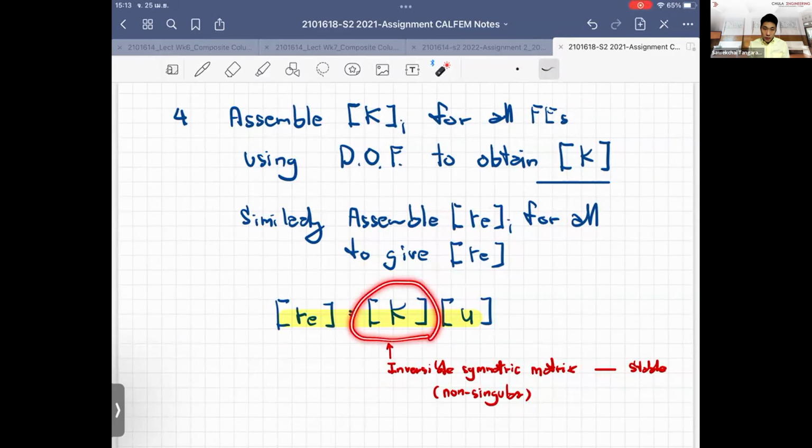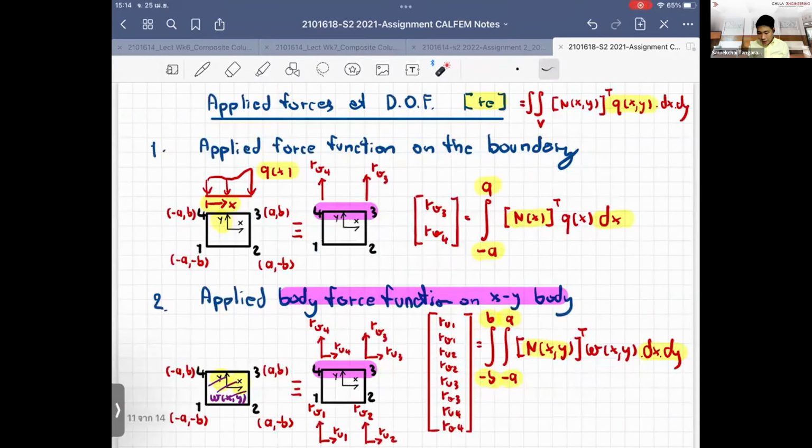So the purpose is we want to construct the stiffness matrix, and this is what we discussed from last week. And we had the CALFEM, and we just want to talk about that as well. Okay, you have already set up the K stiffness matrix. You need the force matrix as well. If you have the force applied at the boundaries, and it's a linear force, it's easy because you can just simply use the average areas between the nodes, right? And times the values of the force.